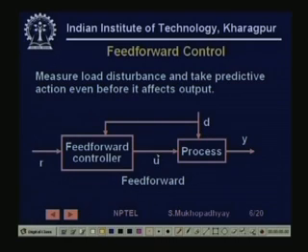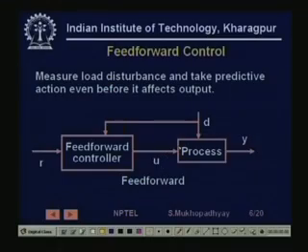This must be known beforehand, because suppose you know that if you have a 10% change in the disturbance, you need to apply a 5% change in the input. Now suppose that 5% becomes actually 6%, then what will happen is that you have overcompensated and the output will not be maintained. But you have no way of knowing this because you are not taking feedback from the output.